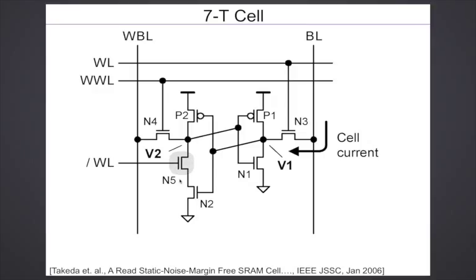And the answer is yes, because again you go back to the discussion we had in the last class. The low voltage limit in some sense is governed by asymmetries between the PMOS and NMOS in the logic cells. And asymmetries can come due to differences in threshold voltage as well as the logic structure, series versus parallel. But that impact is very, very less.